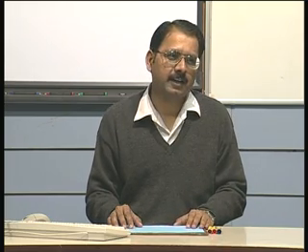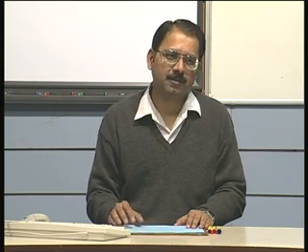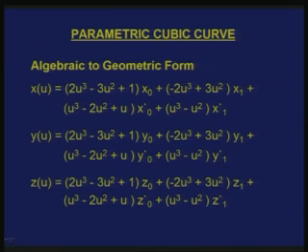You have a slope continuity and you also have a curvature continuity, that means you have a continuity up to a second derivative, which is enough for most design and manufacturing applications. It is very rare that you go for a derivative beyond the second derivative, except in some applications like design of cams and others, where sometimes you need curve forms which are beyond cubic, but for most of the applications this is enough, and this is the most common form of representation.